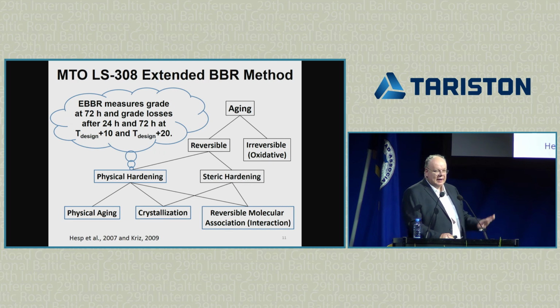So besides banning everything, that's just legal language in a contract, we develop test methods. I'm a scientist, I'm an engineer, and we have worked for a very long time, maybe for nothing, on the development of the extended BBR test, which is simply a modification of the regular BBR, and it cools your sample for 3 days instead of 1 hour. You measure the creep stiffness and the M value, which is the relaxation rate, at 3 days rather than 1 hour.